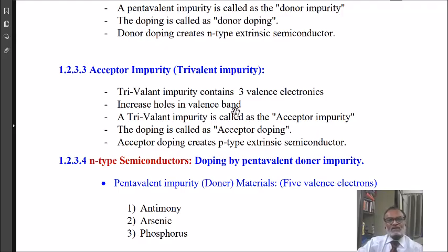Here, we are ignoring the thermally generated hole electron pairs. Whereas when the semiconductor is operated at room temperature, the particles generated, maybe electrons and holes, are because of the impurities added as well as the thermally generated electron hole pairs.